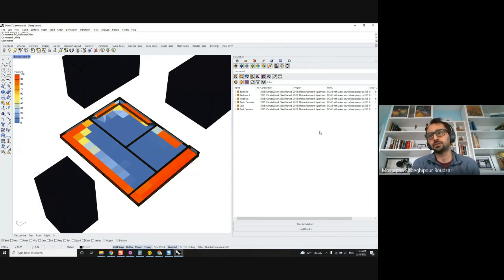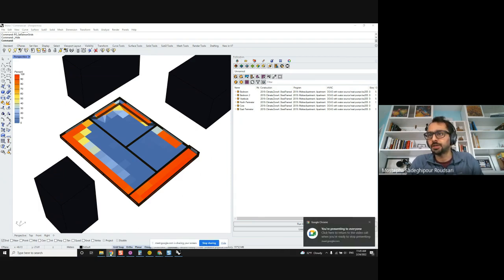But you have to try it. We can use better machines, but we cannot run the energy simulation itself in parallel, except if you use something like a Dragonfly workflow. In that scenario, you can run every floor in parallel, and that can make the whole process faster. This has been discussed before, and we can provide more information.